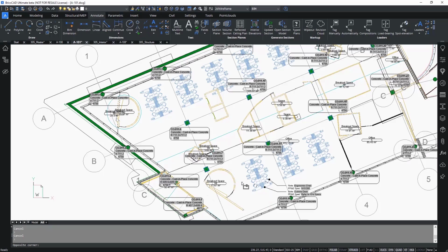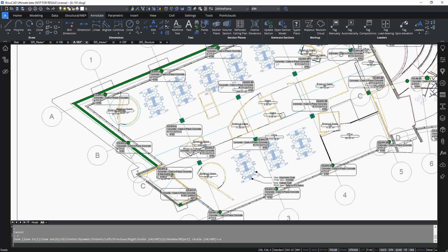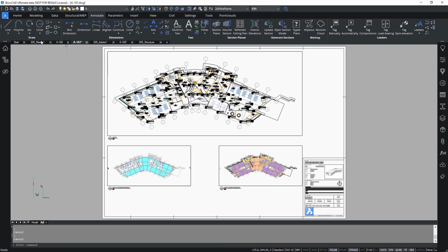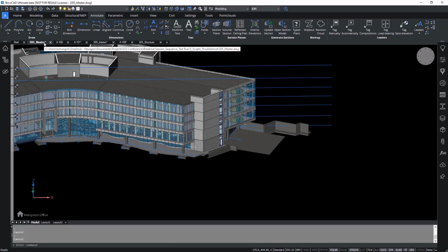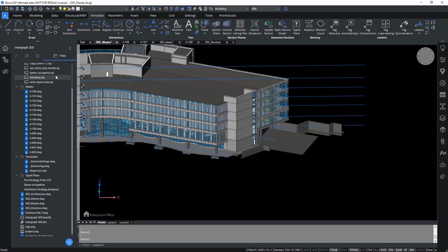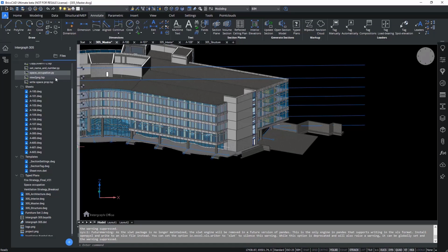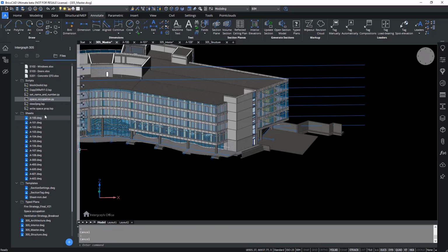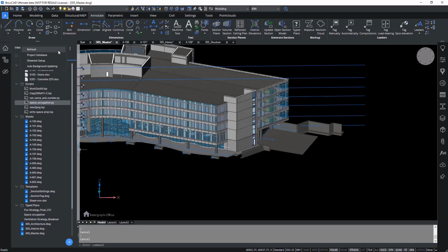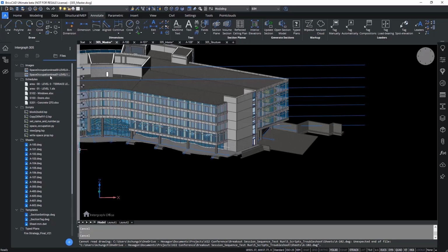One thing to make sure is that you run the .py script in the right .dwg model. So I'm going to run this on the master model where my BIM model is actually stored in model space. Now right-click this space occupancy.py file which I've already prepared. Again, in short, what this script does is generate a pie chart and an area schedule based on the spaces I have in this model. It will automatically create folders to store this information, so when I refresh the project browser, I will see them here.